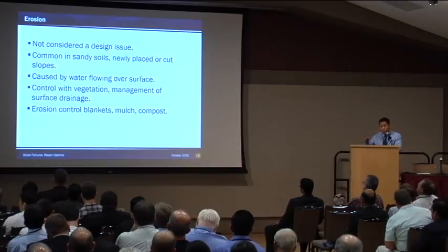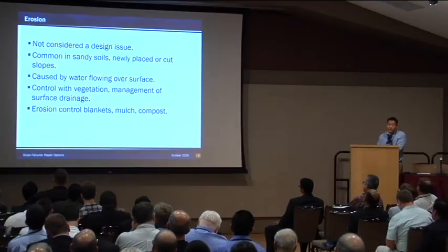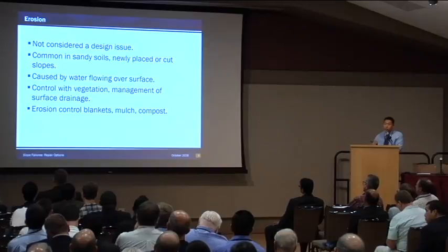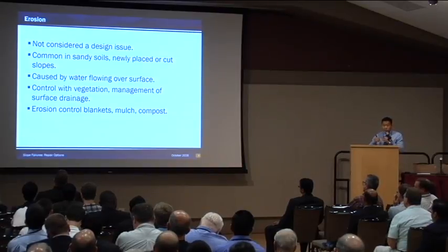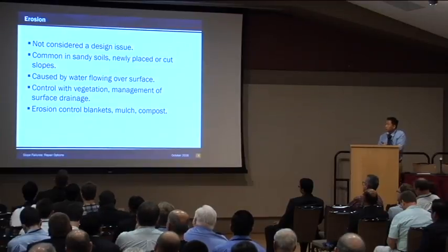So during the design stage, make sure that all the drains are properly installed. Normally, it is very common in sandy soil or silty soil, because there is no stickiness between the soils, so it is very easy to wash out. Then the remediation or control is, first, to control your water properly.